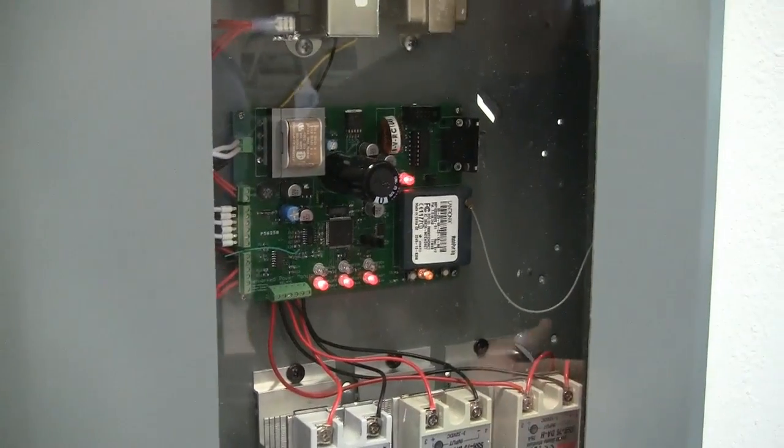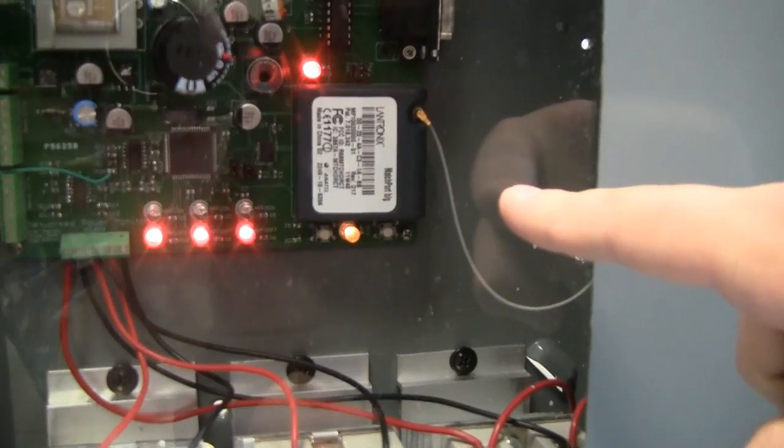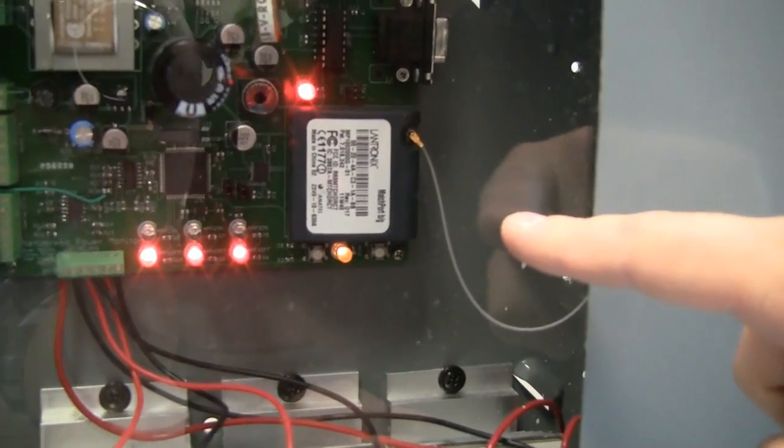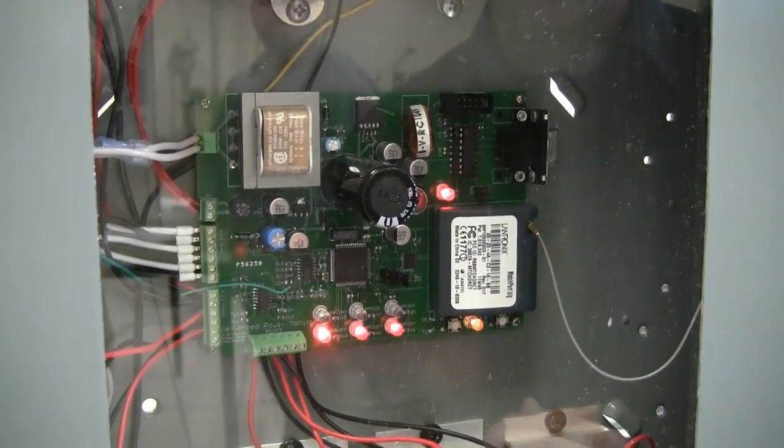A second unique design solution is the Lantronix match port. It is a unified Wi-Fi solution that allows us to integrate directly with our Atmega 128 microcontroller using a UART bus.